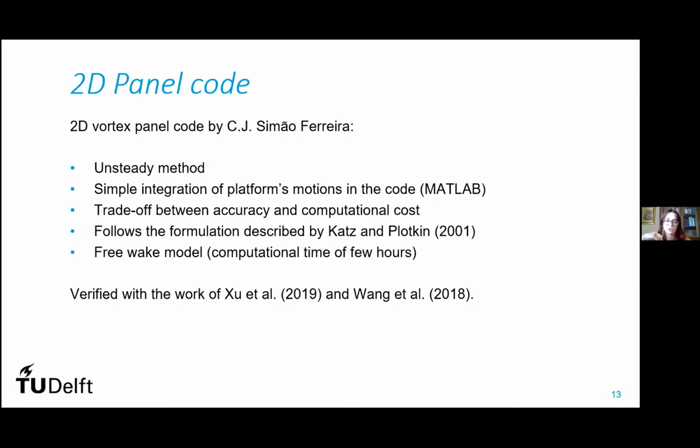during a literature review process. And it follows the formulation described by Katz and Plotkin in 2001 in their book of Aerodynamics. And it implements a free wake model, which means the computational time is reduced compared to CFD, but it is still a few hours because it's still a quite accurate model. And it's been verified in my work with the simulation results from Xu et al.